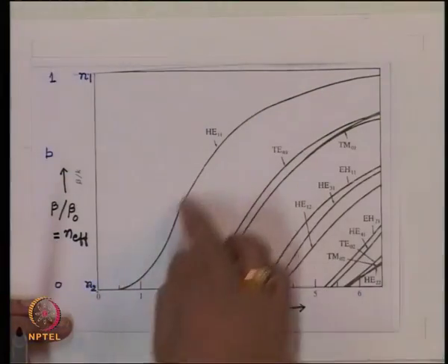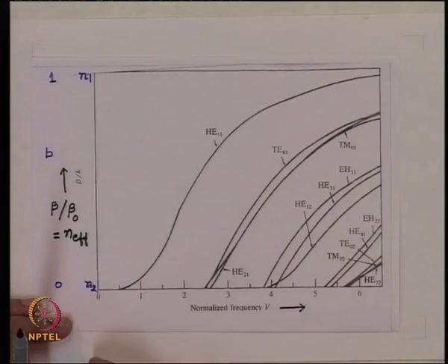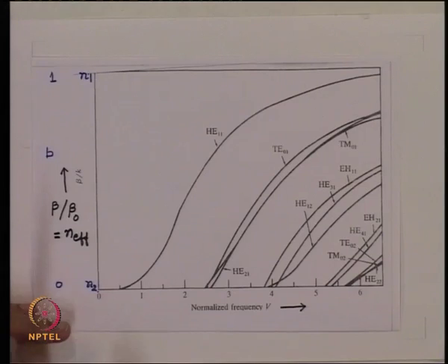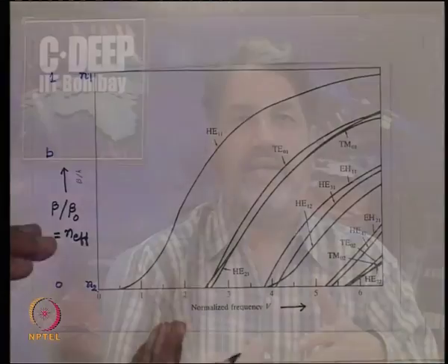So now if I check this back with my ray model, essentially what that tells me is that this mode which is going to propagate here between this and this V number, that must correspond to the ray which was going along the axis of the optical fiber. Because all other rays had to satisfy certain phase condition for total internal reflection.